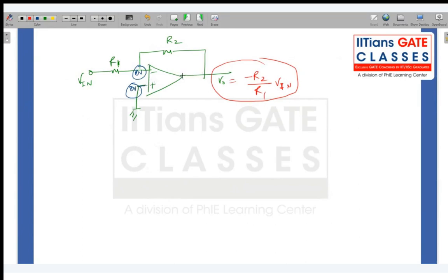In the op-amp circuit, there is a chance that KCL can be violated. You see here, if you are going to apply KCL at this point, you can't apply KCL because the output current of the op-amp is always unknown. You see, there is no current, unless they have given it in the question.